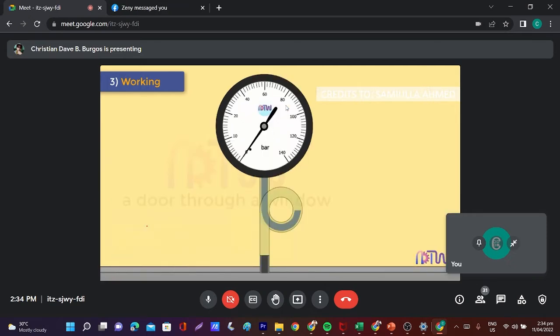In real-life application, the pressure gauges are mounted with siphon tube. Siphon tube is a simple device used to protect a pressure sensor from high-temperature media, such as steam. It can also be used to reduce the potentially damaging effects of rapid pressure changes.